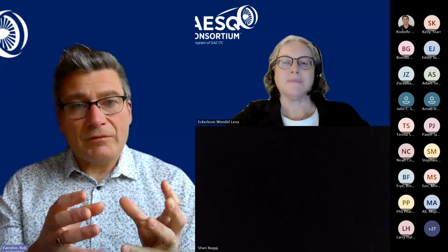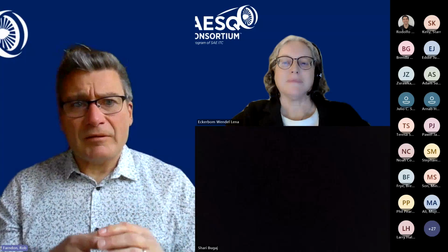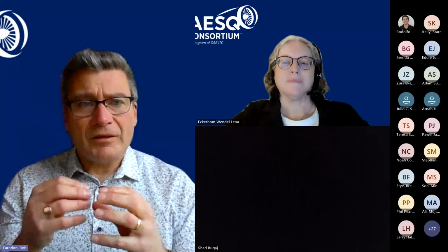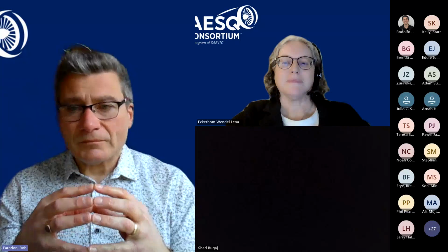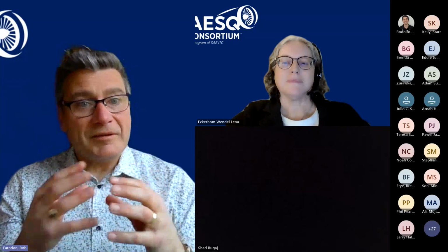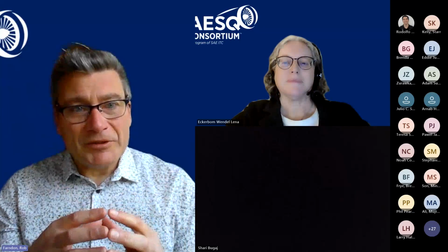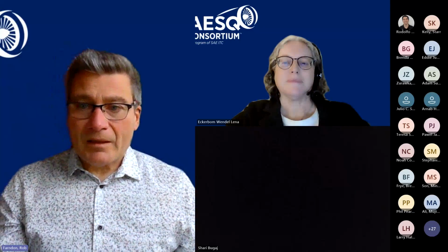You're also trying with a FMECA to evaluate, as you are in a DFMEA, the likelihood of the progression as well as the likelihood of initiation of a failure. And that means that the redundancy argument that we just had, for instance, comes into play in that sort of way.